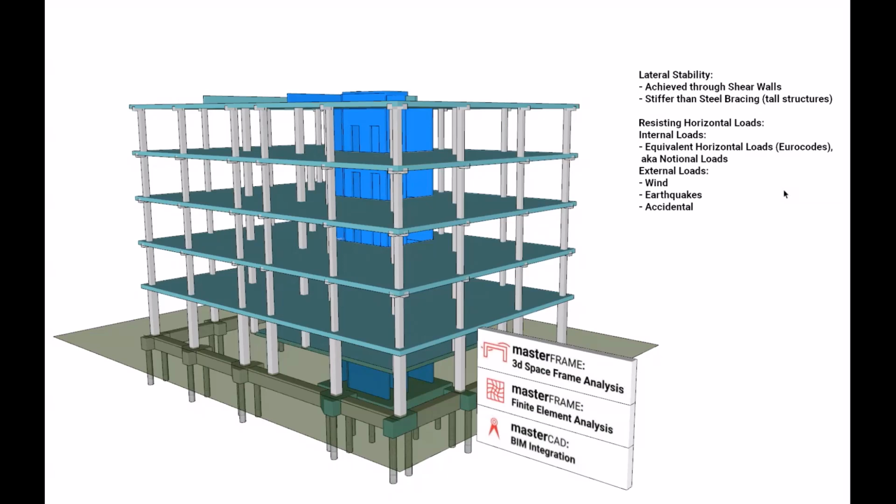I've listed a few horizontal loads that are resisted by the shear walls, and they also do take vertical loads as well. So they can be designed to take all the lateral loads or in combination with the columns as a sway frame, but portalization in concrete frames isn't preferred, as it requires fixed connections between elements, and therefore adds a bit more complexity to the design, construction, and installation of the frame, as well as connections between elements relative to a simple construction with pin connections and a braced wall.